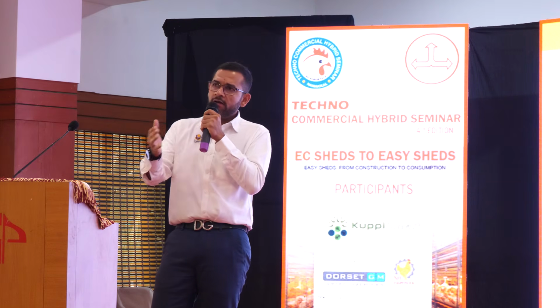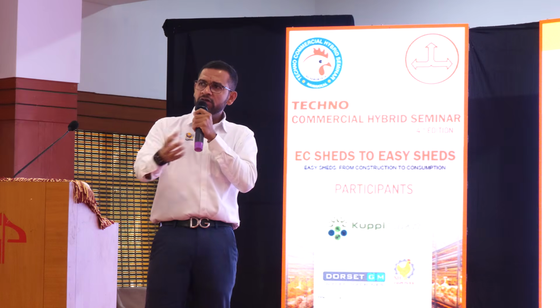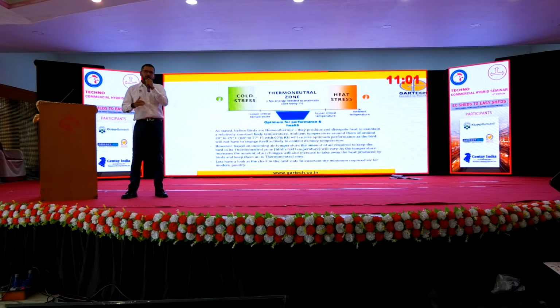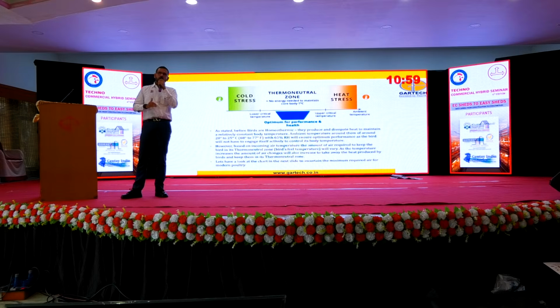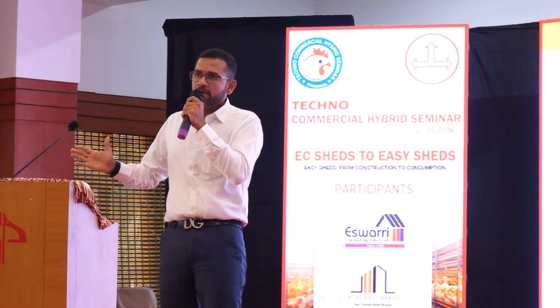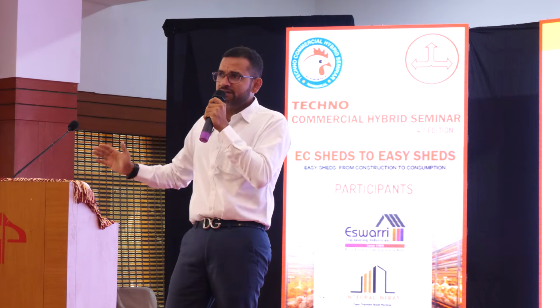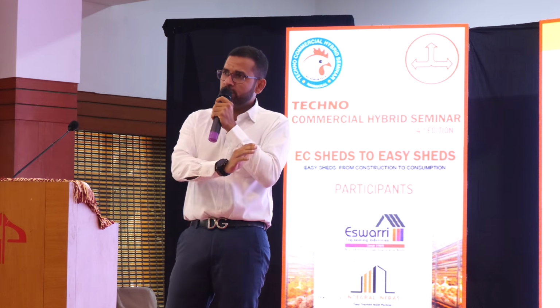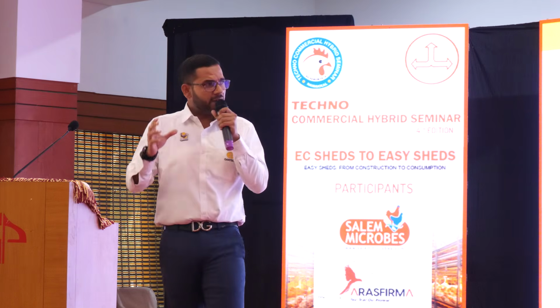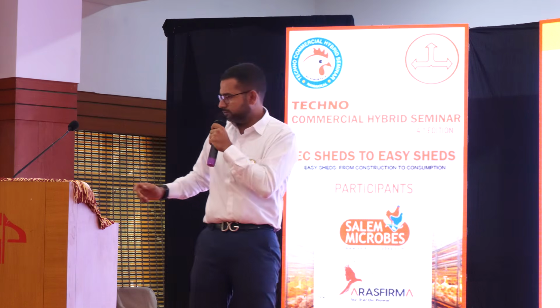So if you now correlate this to the slide earlier, what effectively we are saying is, as the temperature and the relative humidity go up, your air speed should correspondingly go up as well. If this is not happening in the correct fashion, then no matter what you do, you are not going to get the right kind of environment inside the house.